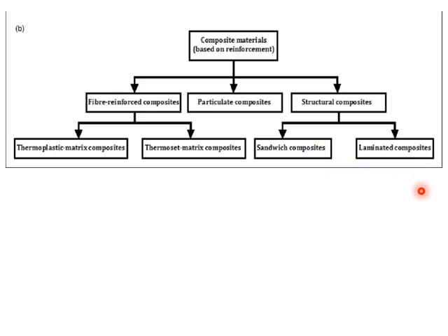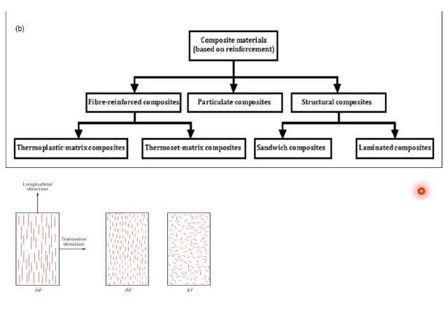So how these things are visible to you, you can see, this is a discontinuous fiber. And we are going to have a continuous fiber here from top to the bottom. So that is a continuous fiber. Discontinuous fiber again has two classifications, uniformly oriented and randomly distributed. You can see in the picture, the picture itself speaks of the difference between uniformly oriented and randomly distributed.